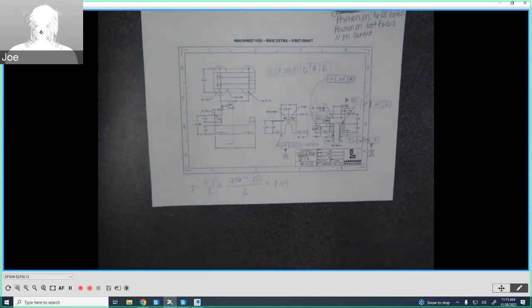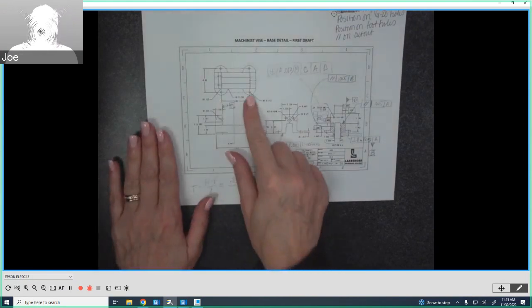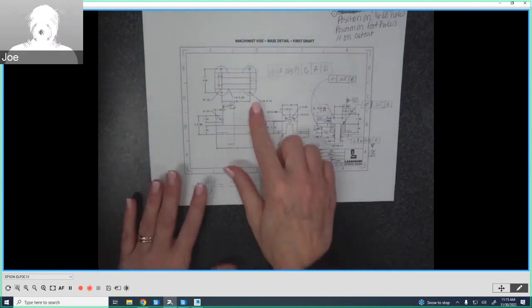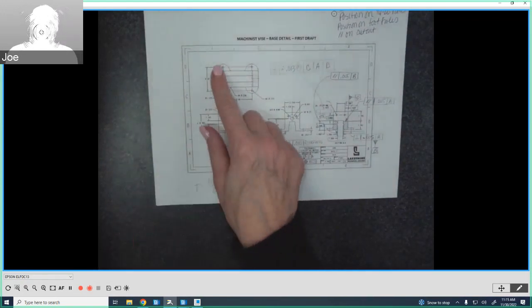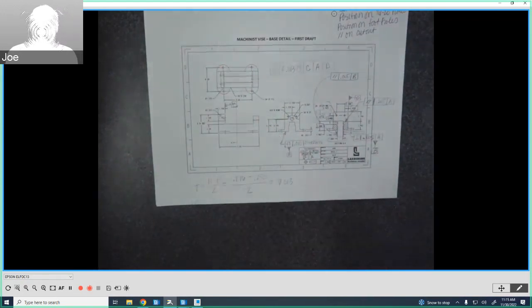Yeah, if you are installing a vise, you're just going to drill the holes where they end up. Right. And again, I don't want to make it sound like position tolerance makes it more critical, because in most cases it doesn't. But remember, these are really large holes, and in many cases you may even see slots for them. So you've got room to play with.